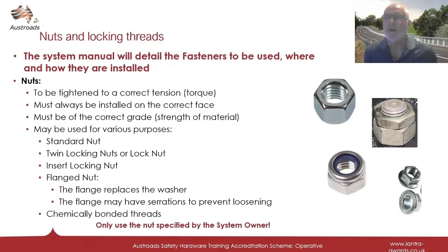Nuts and locking threads. The system manual will detail the fasteners to be used, where and how they are installed. Nuts must be tightened to the correct tension, torque, must always be installed on the correct face, must be of the correct grade, strength of material, and may be used for various purposes.